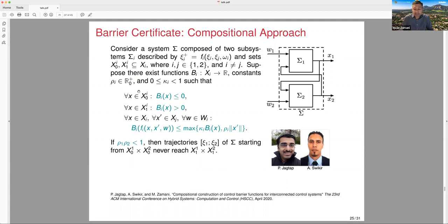The abstraction remains fixed. You compute it offline one time. The controller is a search over a graph of the abstraction, and that also takes around 100 milliseconds. So we are able to do that. We just resynthesize the controller. It's a game over a graph, right? And then we compute the new controllers given the new environment. If there is an obstacle, we just redesign the controller algorithmically. No learning involved.